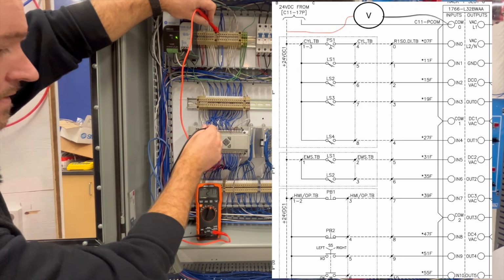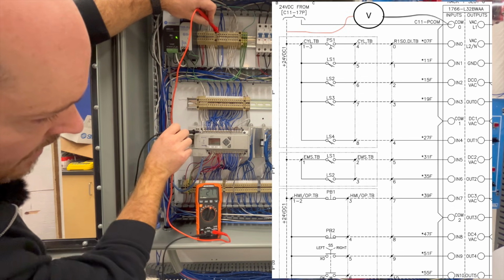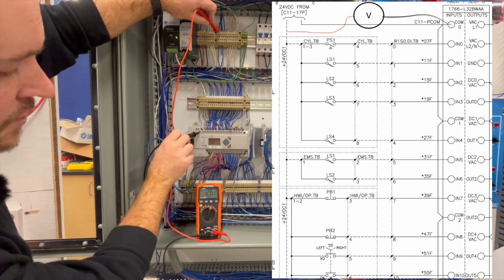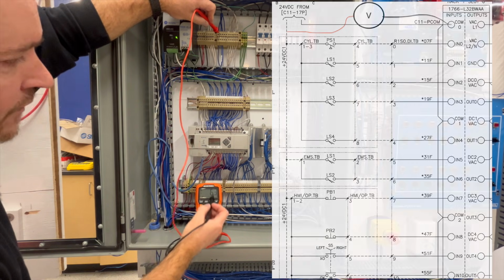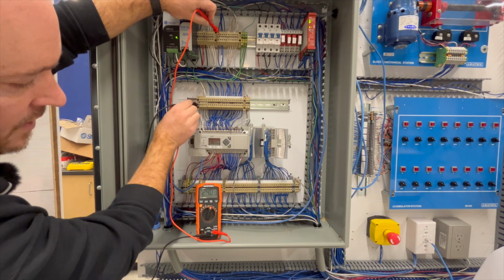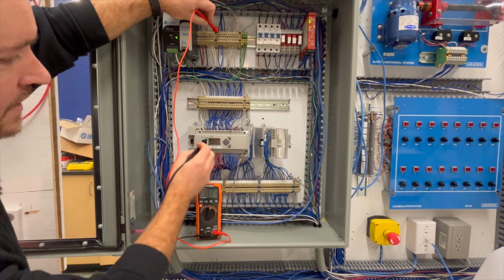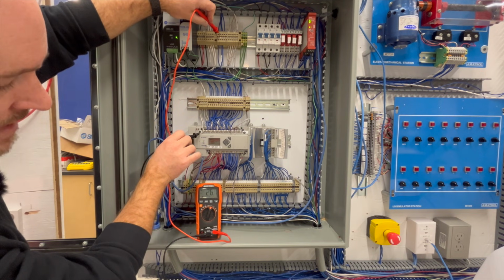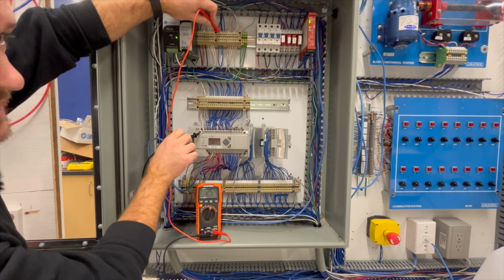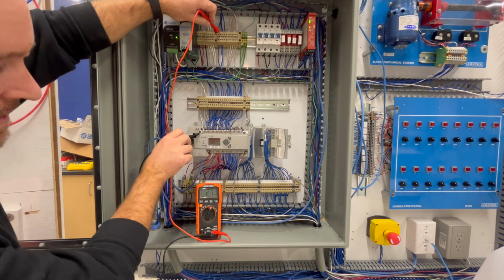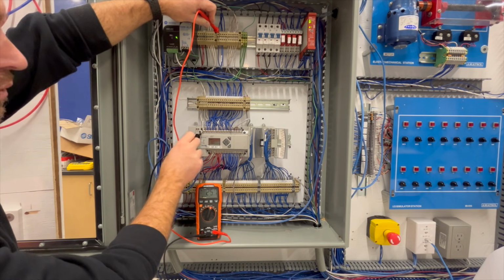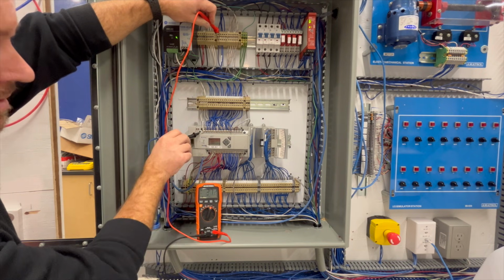So I come here and I am not getting 24 volts. This says millivolts here. This is not the 24 volts that I'm getting here. I don't know if you can read this, but there's a millivolt here. When I come in here, I'm getting 26 millivolts. That is something you have to really pay attention to, because you may think, oh, I'm getting 28 volts. It should work. Maybe my PLC has gone bad.